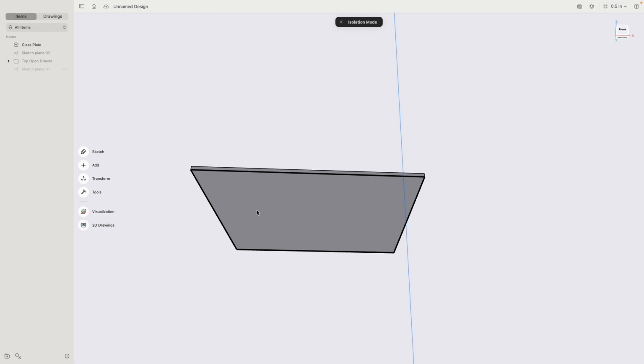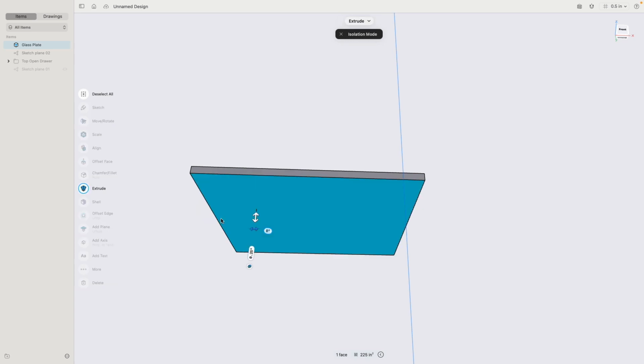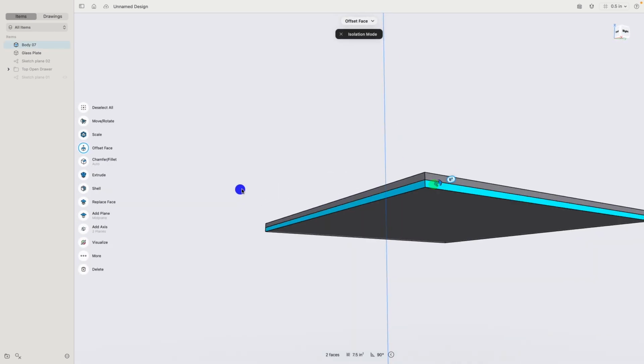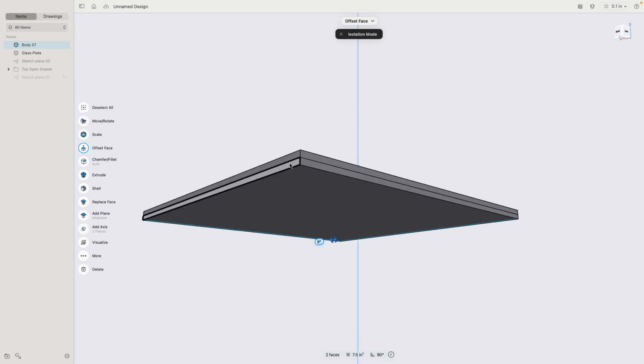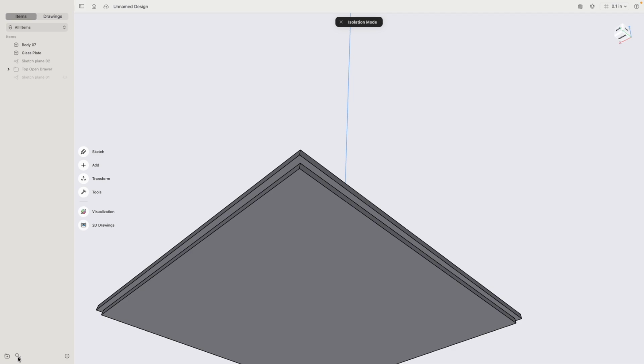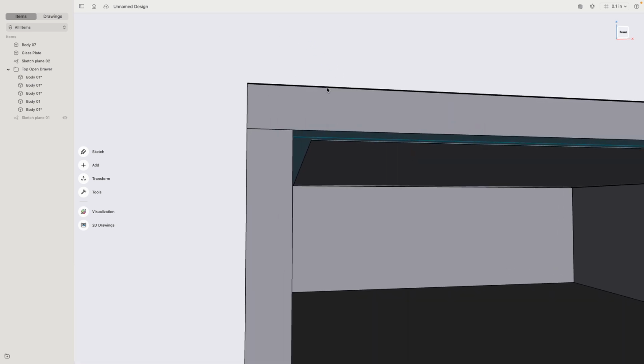Now, take a look at this. I will select this lower face one more time. Click extrude, type in 0.5, 0.25, I'm sorry, and then change the mode to new body. This is actually going to be the geometry that is cutting the smaller opening. So you see I selected all the outer faces and then I type in -0.25. So I'm shrinking the sides by a 1/4 inch. Okay, now exit isolate. We can open this view.